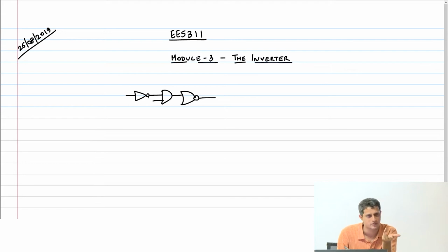In fact, there are capacitances at all nodes. So effectively this will have some load capacitance, plus its own capacitance, coming from the drain, source and all that. We will look at the origin of these capacitances.